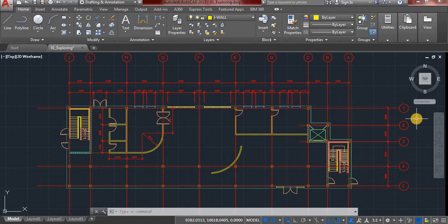Also, I would like to mention something just very quickly so you could pay attention to it in future videos or any file that you work on. Below the viewing cube, you see this, I have unnamed, maybe you will have a different name. So if I click on it, it shows what system it's showing. It should be on the world coordinate system. I'll click that. It doesn't change anything in the drawing, it doesn't change anything that you can see, but it should be this one, WCS.